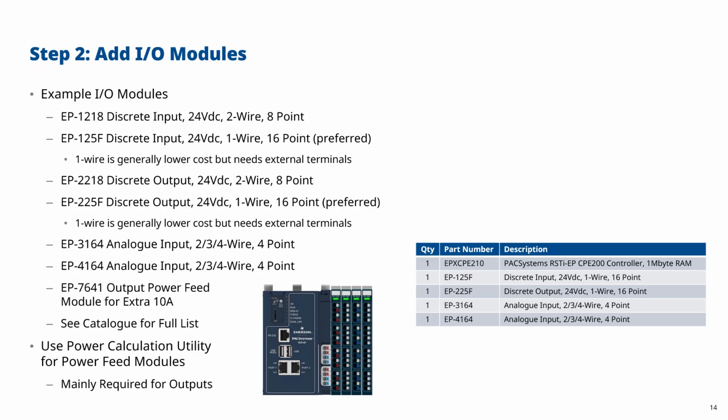So what you could do is a calculation based on the output current plus the simultaneity factor, which is how many outputs are on at any one time. The reason we do that is with many systems, if you're controlling, for example, a pneumatic cylinder, there's one output for energize and extend, and there's another output for de-energize or retract. They're not on at the same time because that would be pointless. You can't retract and extend at the same time. You might even end up damaging the system. You'd certainly be wasting air, and the system probably wouldn't move, or maybe it would move very slowly in a random direction, depending whether the extend or the retract is more powerful.